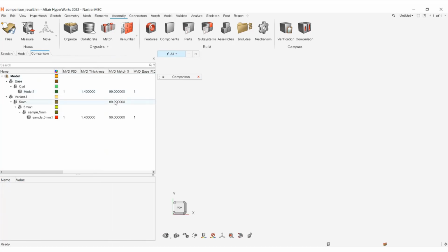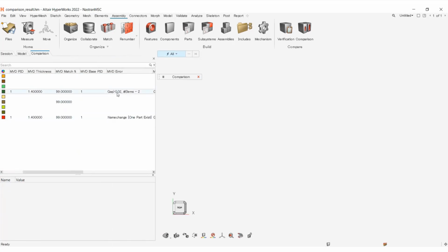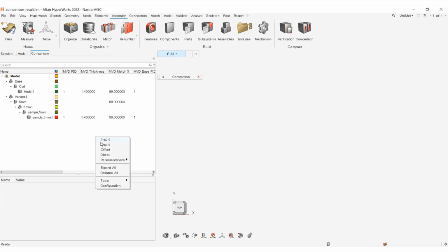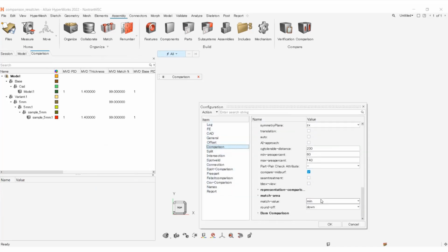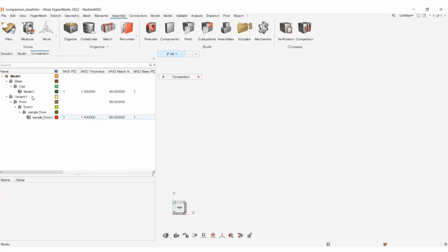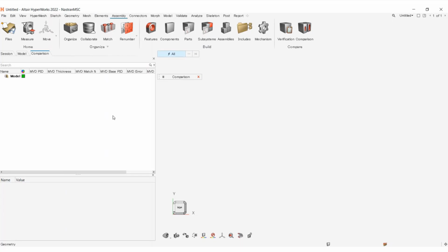It shows 99%, and some of the elements are more than 0.02 millimeter. Customers say 0.02 millimeter is negligible. Usually up to 0.1 millimeter they allow for correcting warpage, so 0.02 millimeter is really very small and we can ignore it. So turning on this ignore minor changes option, we will now rerun the whole comparison and you can see the results.